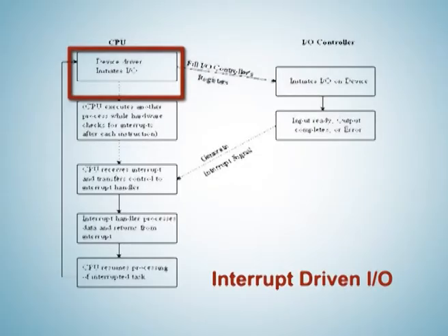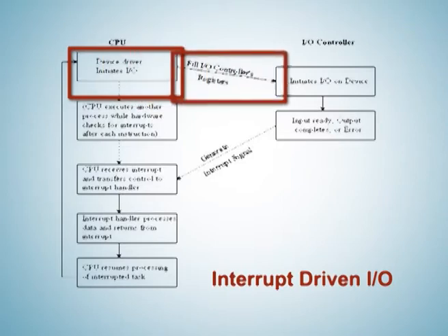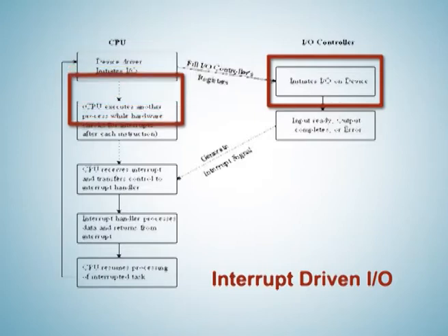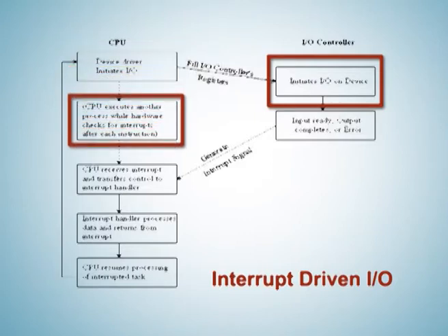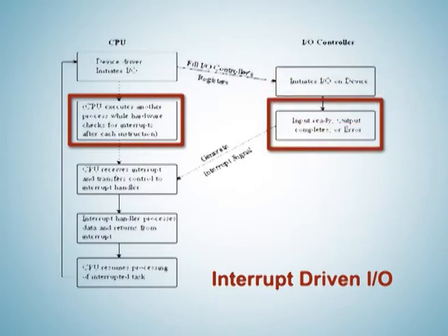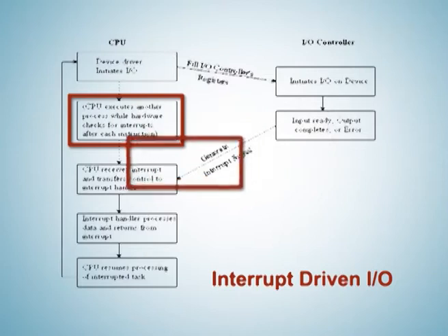Using these commands, now let us understand how an interrupt driven I/O is performed. For input, the processor issues a read command. The processor knows that the device is slower and may take its own time to deliver data. Meanwhile, it switches to some other program instead of waiting for the device. When the device is ready to deliver data, it sends an interrupt signal to the CPU.